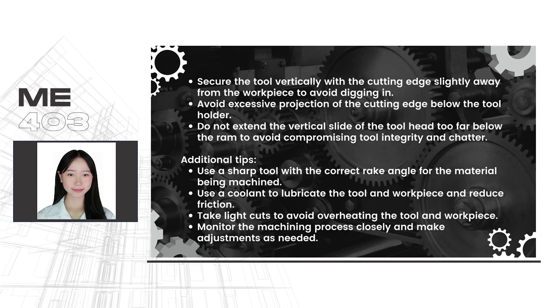Eighth, avoid excessive projection of the cutting edge below the tool holder. Lastly, do not extend the vertical slide of the tool head too far below the ram to avoid compromising tool integrity and chatter.